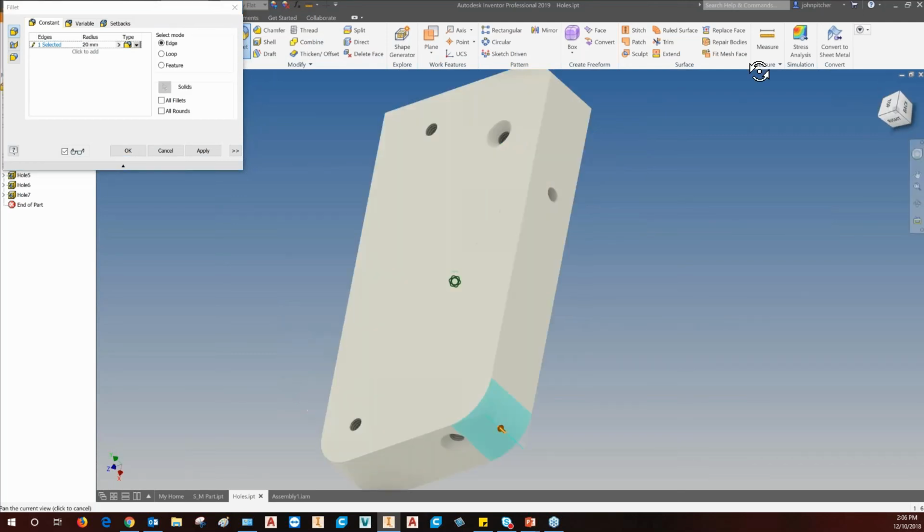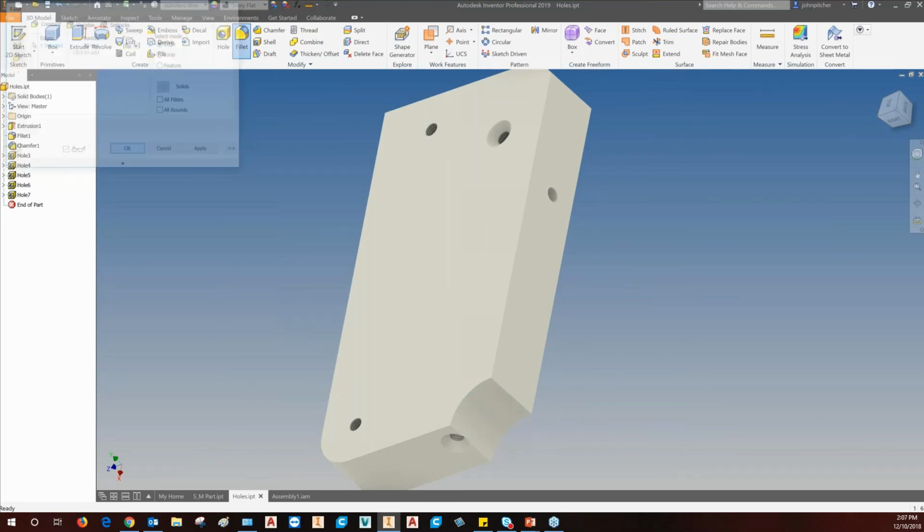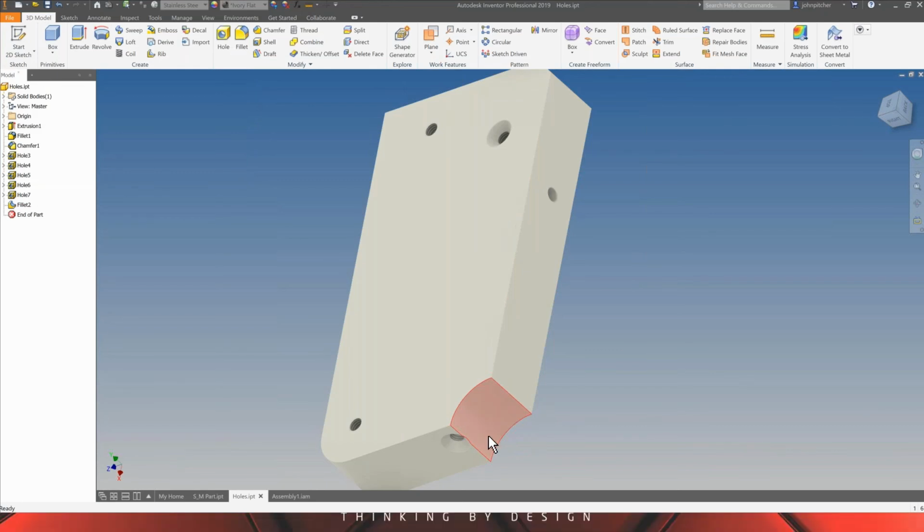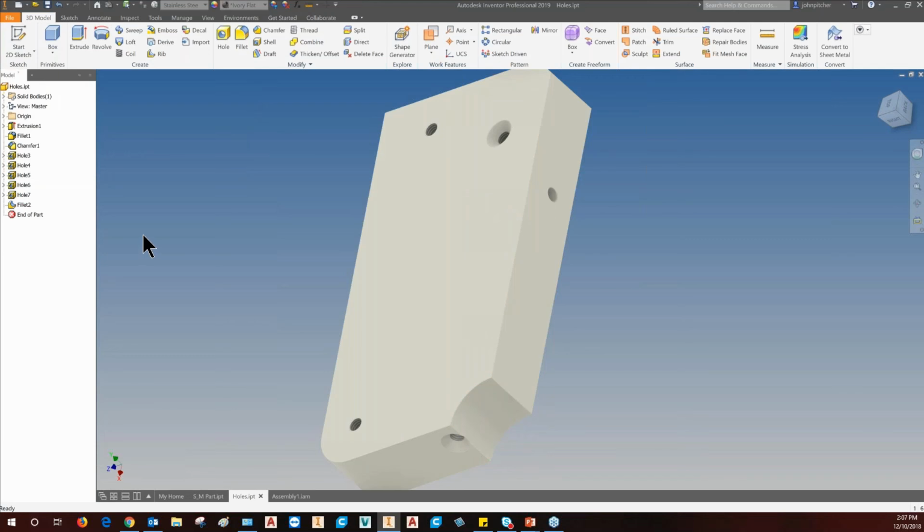This drop down allows me to pick a tangent fillet, a G2 smooth fillet, or a reverse fillet. So that's quite a neat little tool as well. There was a workaround for this previously, but this is another option for creating a reverse fillet. Quite handy to be able to quickly generate reverse fillets there.